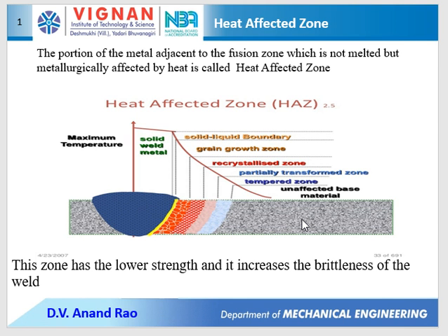Because of this heat affected zone, the strength of the weld will reduce, and at the same time it increases the brittleness of the weld. Due to the increased brittleness, the strength will reduce and it may suddenly break whenever we apply this welded joint for any application.